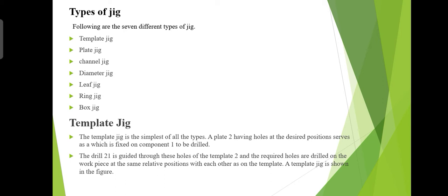A simple example of a clamp jig is a design for drilling holes that are all the same size, for example, the stud holes in the cylinder head. It is frequently attached to the cylinder head and held by U-bolt clamps when used as a guide for the drill in the drilling operations. The jig makes certain that the holes are in correct locations because the holes in the jig were originally located with precision. Therefore, laying out is not necessary.